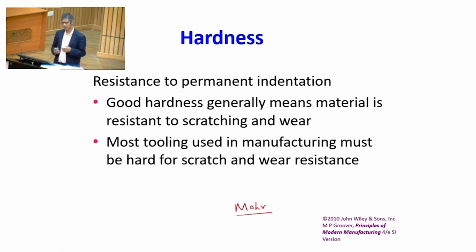Okay. You can always use hardness as one of the ways to measure the material's mechanical properties, because in many cases you may not have the facilities to measure the tensile strength, and you may not have the sample also to prepare a particular geometry of sample. So, in that case hardness is the only way to measure the mechanical properties. Okay. This indicates